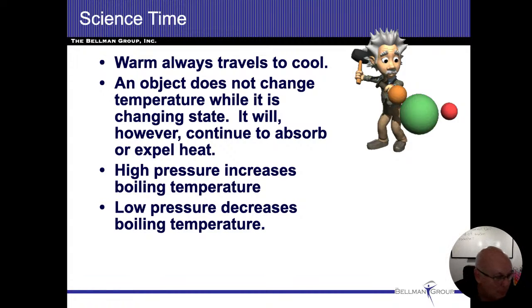So 1 pound of water, 1 degree Fahrenheit. If I have 1 pound of water that's 50 degrees, and I want to raise it and make it 100 degrees, I hope we're realizing I have to add 50 BTUs to that. And that's how long the fire has to burn and how much gas needs to be used. If I want to go from 100 degrees to 200 degrees and I still have that same 1 pound of water, then we're going to be using 100 BTUs.